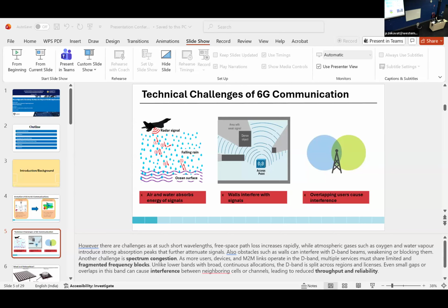And then when the diodes are on, it switches to absorber mode and achieves 90% absorption across 2.8 gigahertz to 5.2 gigahertz. Also, a prototype was fabricated using PCB technology, validating the simulation. So therefore, this study offers a compact and tunable solution for adaptive electromagnetic interference suppression and also stealth applications.